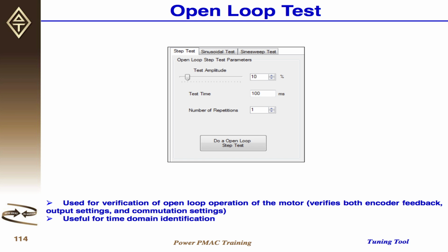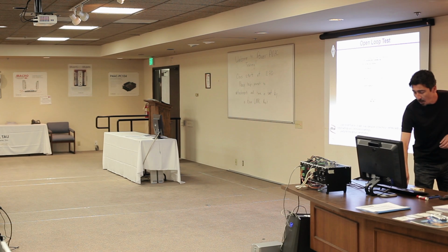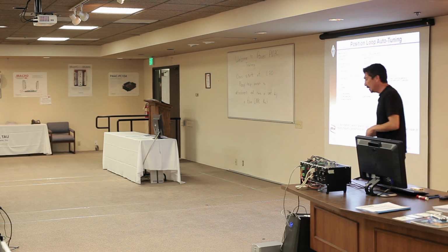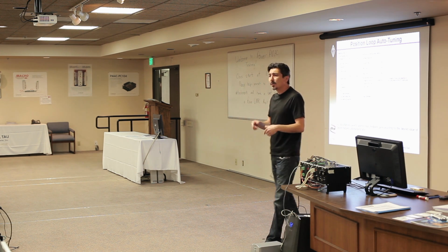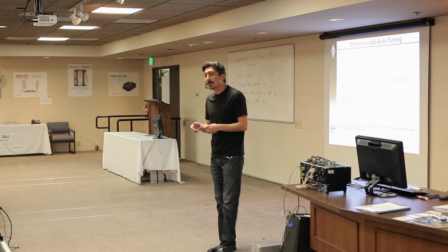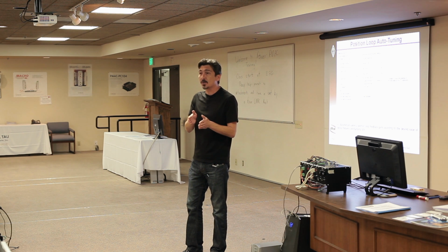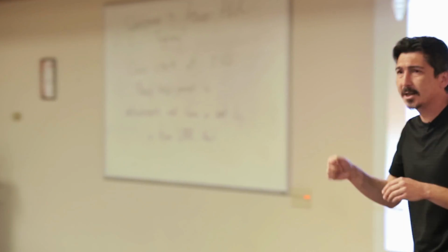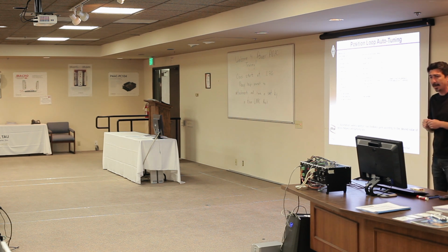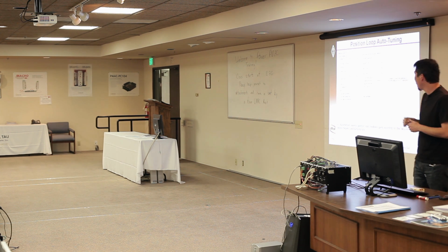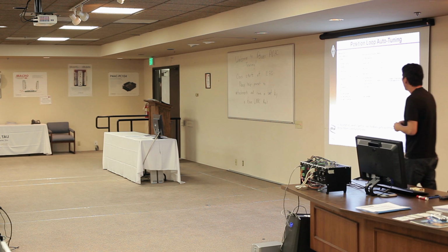And that's basically going to be a good tool to understand the dynamics of the open loop. It's also really useful in terms of seeing if you have any resonances, if it's at really low frequencies. At high frequencies, you won't be able to see those. If you have a resonance or flexibility in your system which is high, you won't see that. But if it's really low, you'll be able to tell it.